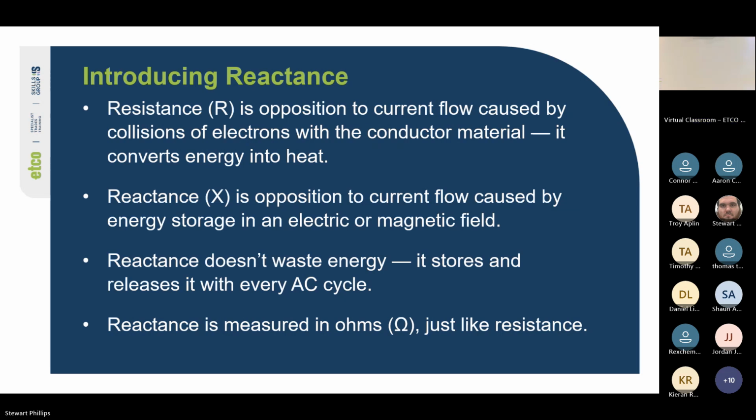So when we talk about our resistance, it's the actual resistance in the copper in the windings inside of the actual load itself, or what we would consider the thing that's doing the work. Whereas our reactance is the charging and discharging of the capacitors and the creating and collapsing of the magnetic field.